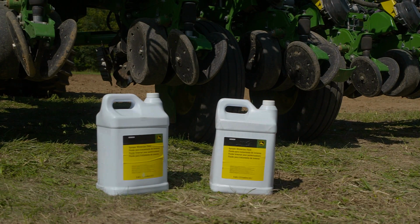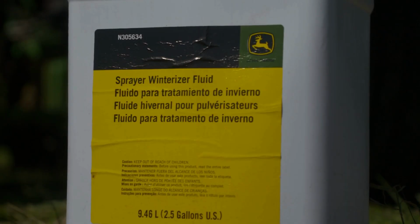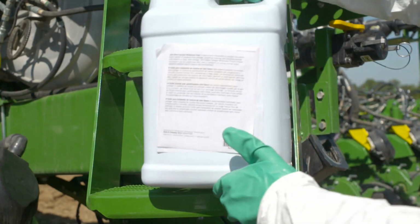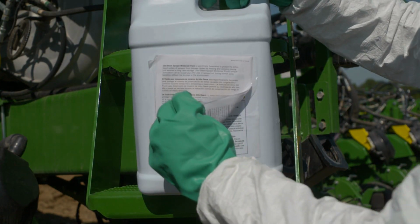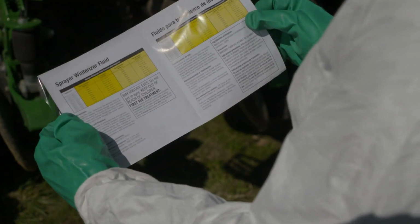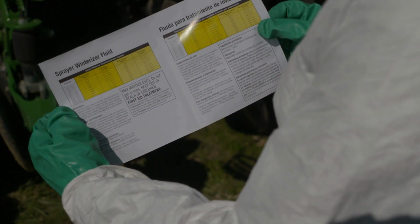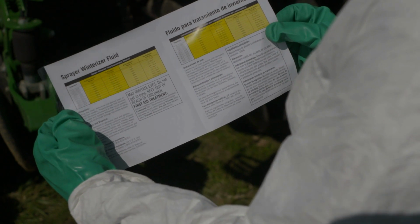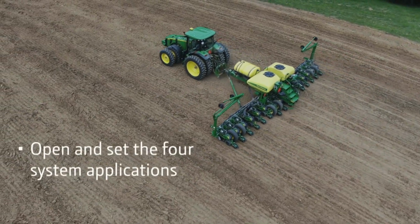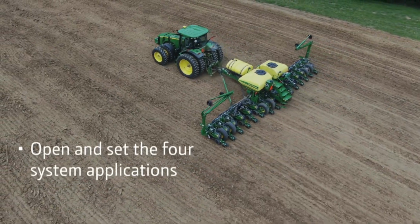Always use a winterizer solution to flush the system if temperatures will fall below freezing and for long-term storage. Note, do not leave water in the system for more than a week as algae may start to grow. Refer to the Clean Out and Winterize video in this series for more information on the Rinse System app. Now you should be able to open and set the 4 applications that run the ExactRate system.